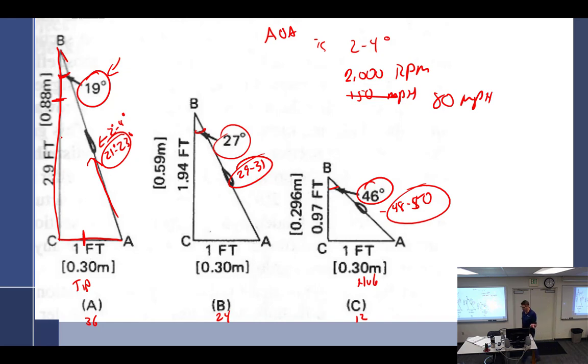So I told you a second ago, when you have your feet on the brakes with the fixed pitch propeller and you throttle forward, it's called static RPM. It's a published number in the type certificate data sheet. You've got to hit it. Not less than, not above. What if you go less than? Engine's not producing enough power. What if you go over? Engine's producing too much power. Your pitch is too flat and you're going to overspeed.